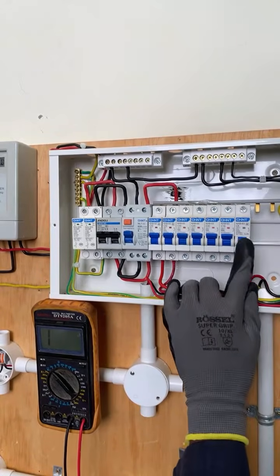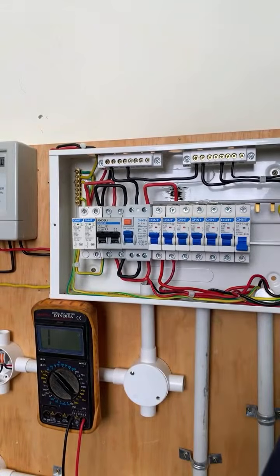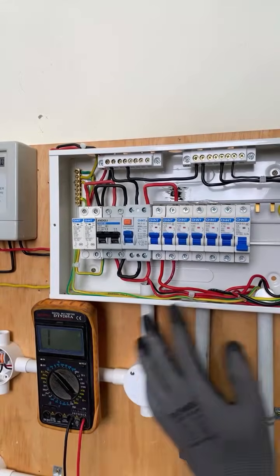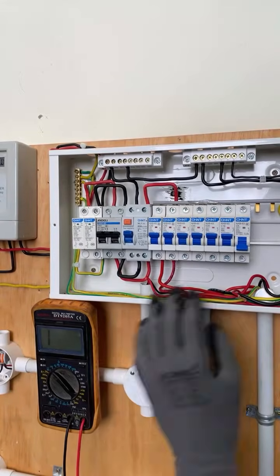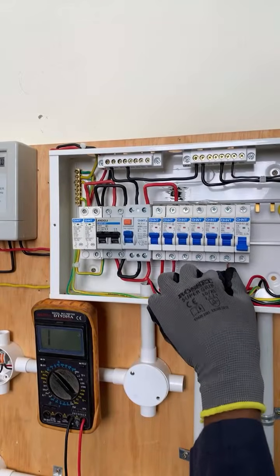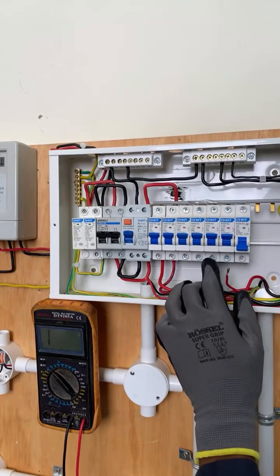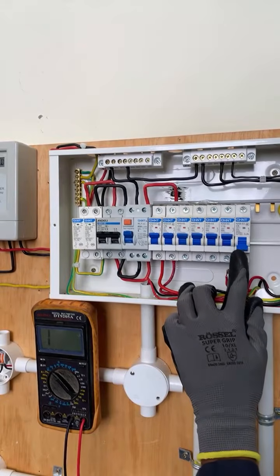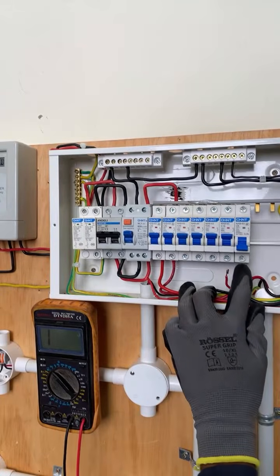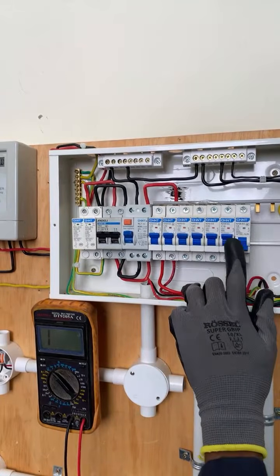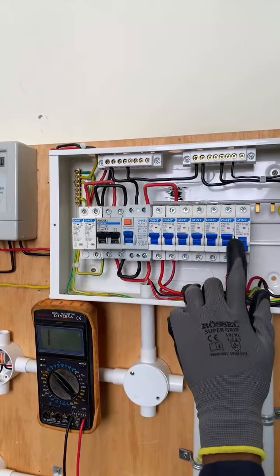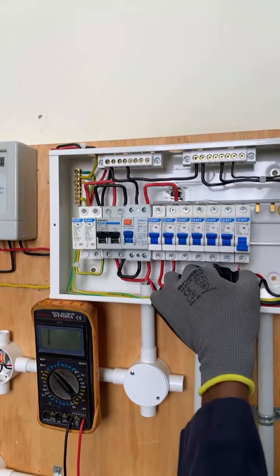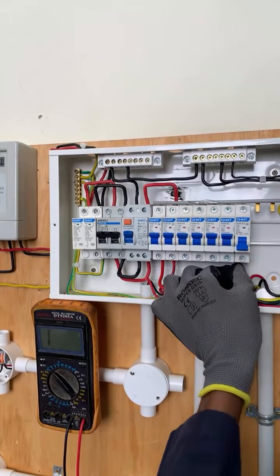If the problem was with the MCB, you'll find that after doing all the checks and ascertaining that there's no problem, you reconnect it, and after the lights are on, it trips again, you definitely know there is a problem with this. Especially after taking the readings, you can also replace it, because it's just one MCB, you can replace it with another. If it doesn't trip, it's a clear indication that that MCB was the one with the problem.